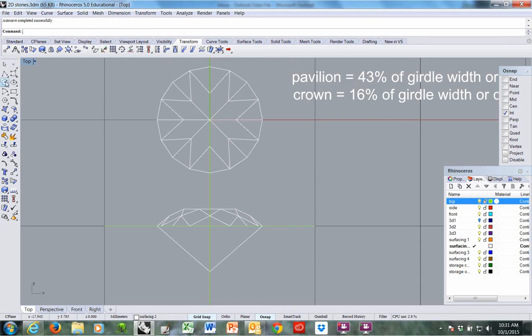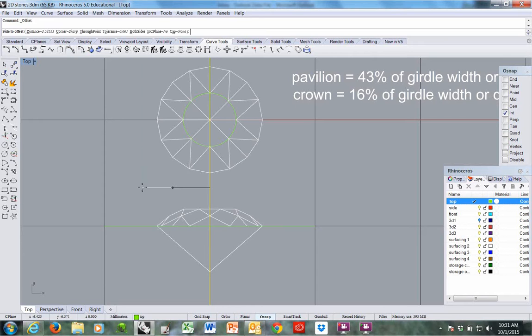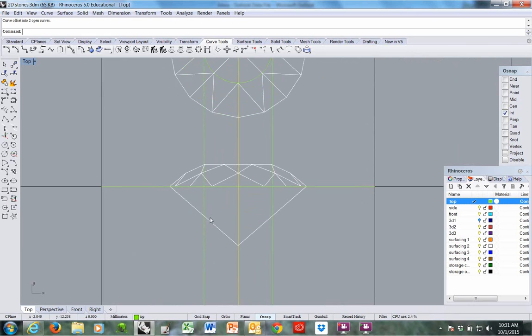The first step is the same as it was for drawing the technical drawing of the crown. Circle, center, radius, pulling out to this point to show that we need this elevation. The information we can bring from the top view for that will be its widest point, so we'll offset our construction line on both sides and bring that down. Okay.